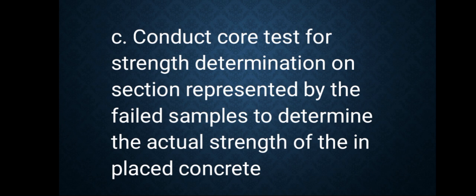the placed concrete. So, why is this the answer? Because when a set of 3 beam samples representing a particular section of a concrete pavement failed to meet the flexural strength requirement, it is the right of the contractor to take it further by conducting a core test. So, let's proceed to number 52.